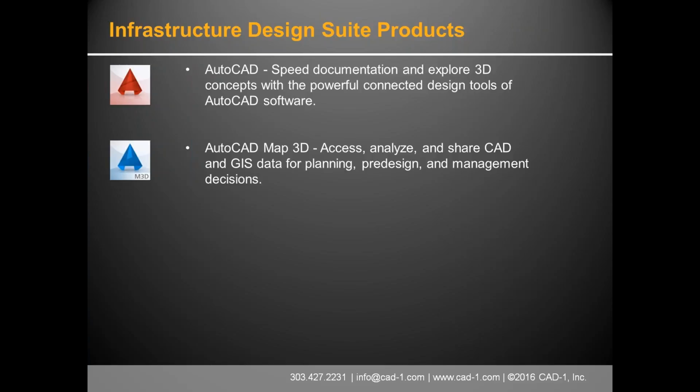Map is a great tool. It does more than just topological analysis. It really helps you take AutoCAD to the next level. It brings in shape files and SDF files and can do different types of analyses. It gives you access to all that wonderful, free, for the most part, GIS data that's available out there. So yeah, AutoCAD Map is fantastic.